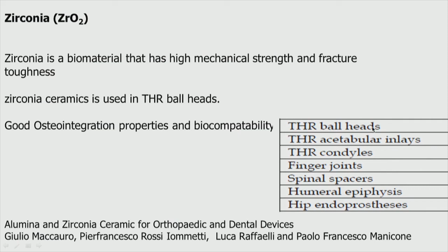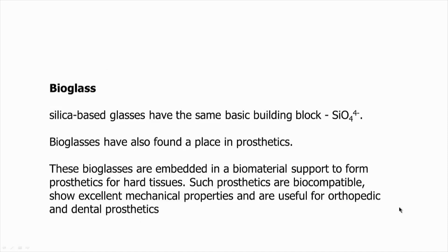So, total hip replacement ball heads, acetabular inlays, condyle, finger joints, spinal spacers, humeral epiphysis, hip endoprosthesis. All these places where you have ball and socket type of moving, zirconia finds application. So, alumina and zirconia have very good applications in orthopedic and dental applications, but zirconia is coming up of late because it has much better fracture toughness than any other bioceramics.